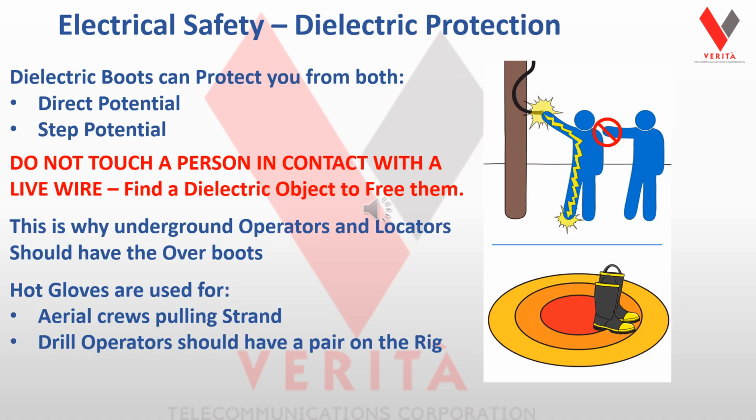Dielectric protection. Now, the dielectric boots can protect you from both direct and step potential. If we look over to the right there, you see the person making direct contact with the energized line. And also he's in direct contact with the ground. You can see the path it takes.